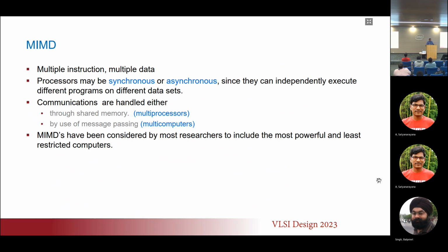When they share the same address space, each core could communicate with the other core just by going through the DRAM or by going through the cache. The last level cache, which is also known as LLC, the two cores could pass data to each other through the LLC, for example. And in that scenario, you can get 128 parallel executions going all at the same time.